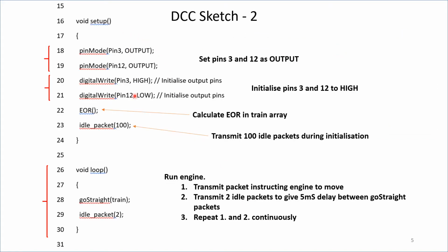Now I have to go through the setup part of the program, and the setup part of the program in Arduino are some lines of code that you only run once at the very beginning. Once you've run these, you don't run them again. It's the loop where you keep going over and over again, running the same code repeatedly. So I'll go through what the initial code setup was. The PWMA pin D3, I've already called D3. I'm specifying that as an output pin. That is, it's going to receive outputs from the Arduino Uno. Pin 12 is also an output pin, which is getting its signal from the Arduino Uno.